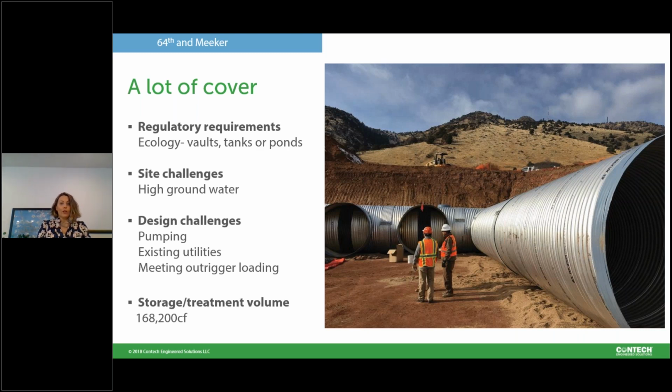The first project that I chose happens to be in Kent, Washington, and at first sight it seems like a regular underground detention system. There's a parking lot, which is pretty common around here, so it seems pretty regular and pretty simple. Regulatory around here, the Washington Department of Ecology allows for vaults, pipes, or ponds to be utilized for detention. We really rarely utilize ponds because mostly the land is really expensive and nobody really wants a big gaping hole on their project sites.